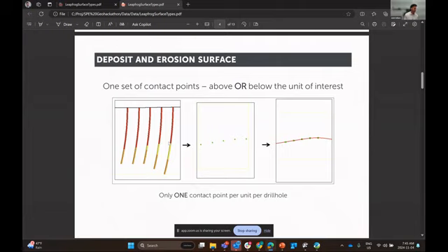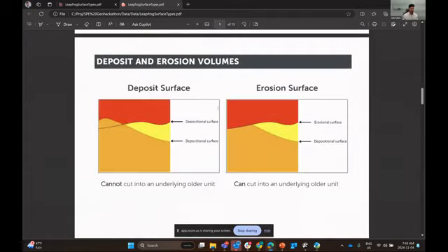Leapfrog is using the FAST RBF, that's a radial basis function surface building algorithm, to build a best fit surface based on the input data points available. So it converts this categorical information to numeric information where we see zero values, which represents the contact points associated with each one of these drill holes, and builds a contour associated with these zero values. So it builds a best fit surface.